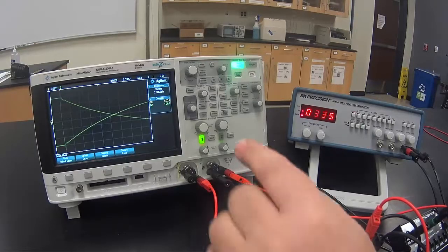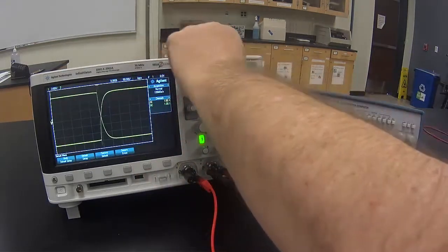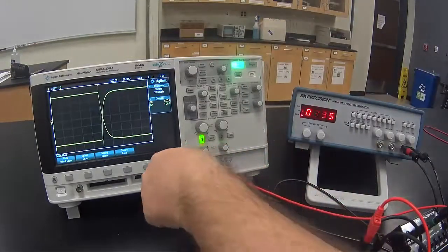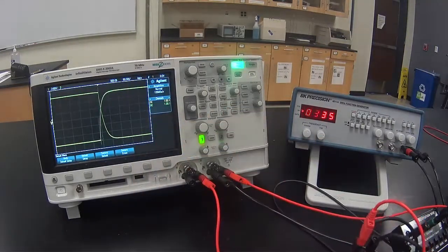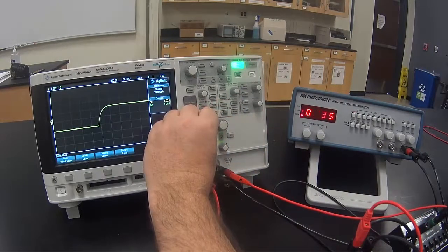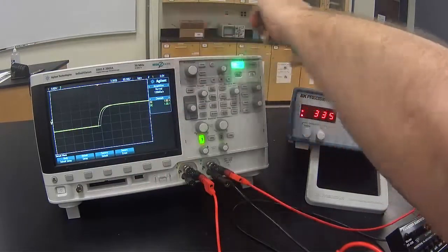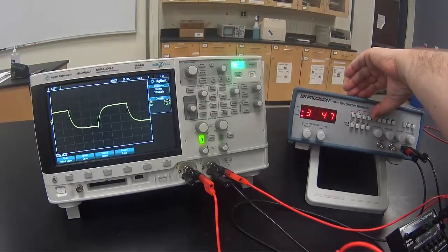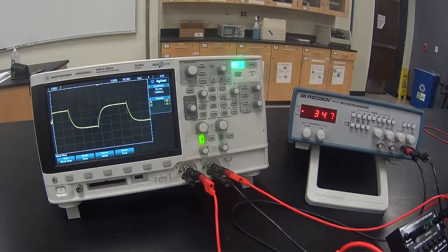Now we will adjust the time sweep so that we can display it like it was originally, with a little bit of curvature, but still we're going to ultimately fit several periods on there. And we're also going to adjust the voltage so that it only takes up about half the space on the screen. So, setting for some curvature and then changing the frequency of the square wave, I can show a few cycles of charging and discharging.